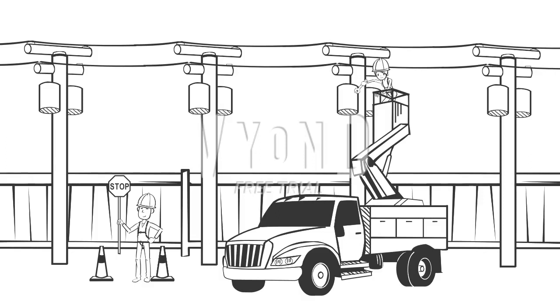Tesla takes its vehicles all the way from rolls of aluminum to completed vehicles at its factory, so its layout has to be immaculate. For example, Tesla got the massive Schuler high-precision high-throughput press for stamping out body panels for the Model 3. Tesla made numerous improvements to the press to increase productivity. They completely reworked the conveyors to fit more functionality into less space. They did this by replacing the 2 discharge conveyor belts that came with the press with 4 shorter belts that fit better into their space.